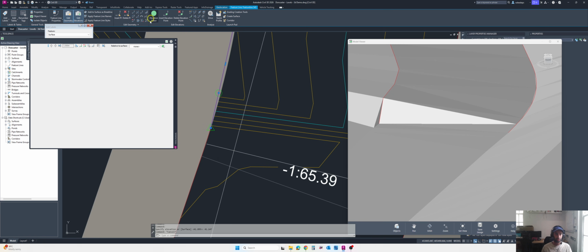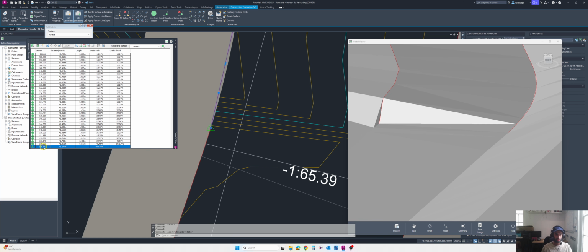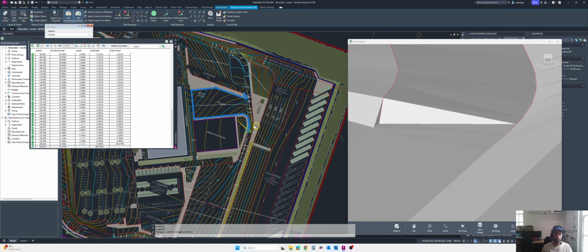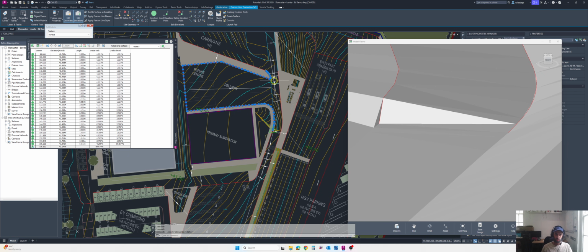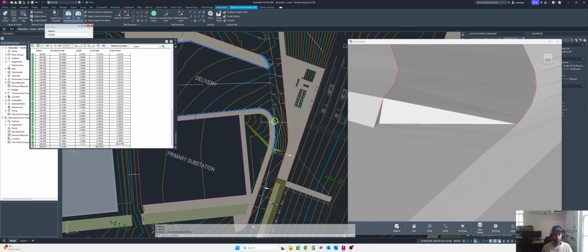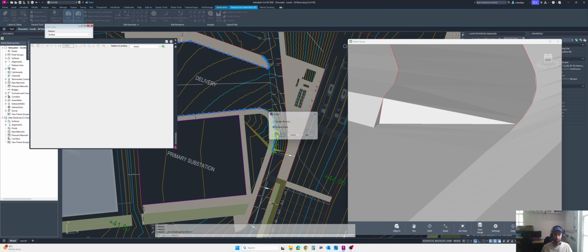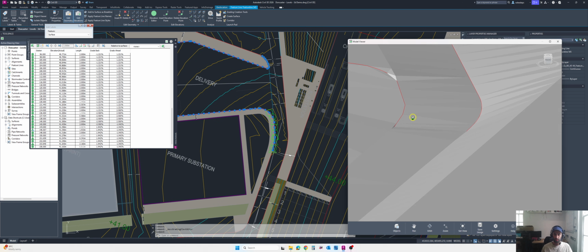And again, elevation editor, select this point. I think, yeah, this one is the last point, and it goes all the way like this, but I don't want to go all the way like this. So just to the curve point would be fine, because after that there's a parking area, so whatever grade is, I don't want to change that because that will impact this whole delivery area. So I will just do this and then do grade. Now it has smoothened it.